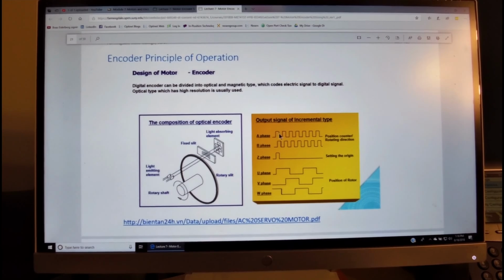In turn they provide a series of pulses, and these pulses typically come separated at 90 degrees. You see over here, and one of them describes the position of an index position, which is a reference for homing or to start counting these pulses.